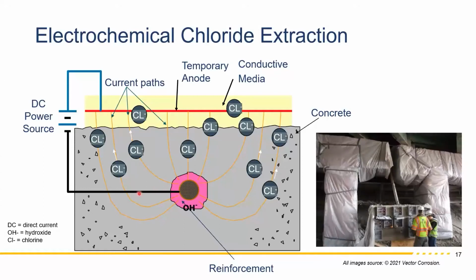So this is similar to cathodic protection, except in cathodic protection you don't have a temporary anode, you have a permanent anode, and you put less current, about 10 milliamps per square meter. This is about 1 amp per square meter. You basically keep the steel from corroding. That's the threshold at which corrosion doesn't happen. But you have to make this a permanent connection.